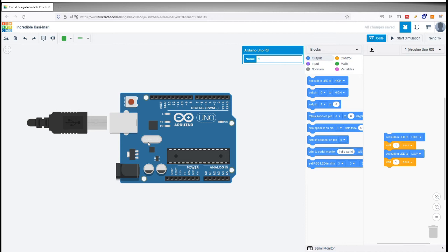So here, the same method you need to use. You need to make the LED on, you need to create a delay, or you need to wait for some time so that I can see the on state. Wait for at least say half a second or 1 second. So I can see the on state. Then I should make the LED off. Again wait for some time so that I can see the off state. So if both on state and off state are kept in my eyesight for at least half a second, then only I can visualize the blinking effect. Right. So that is what we are going to do.